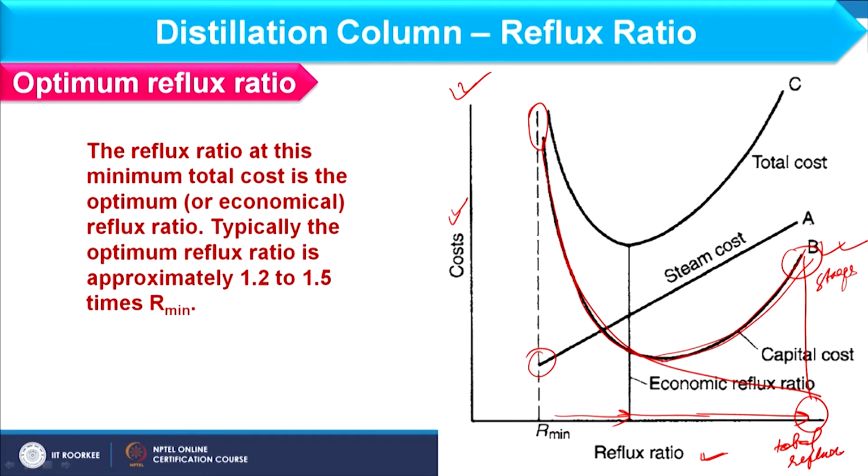However, as the heat duty of reboiler and condenser increases with the increment in reflux ratio from minimum reflux to total reflux, we can continuously find an increment in the operating cost, and if we consider the addition of these two, we can find the total annual cost, and wherever it gives the minimum value, this reflux ratio I can choose as the optimum reflux ratio, right.